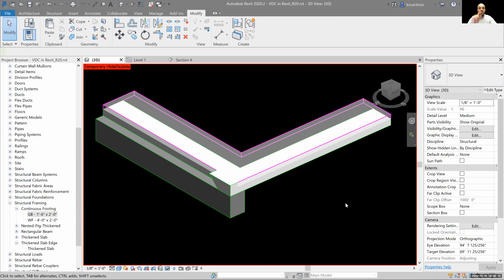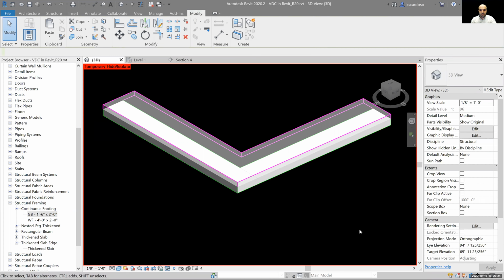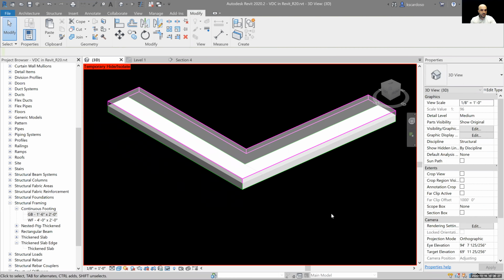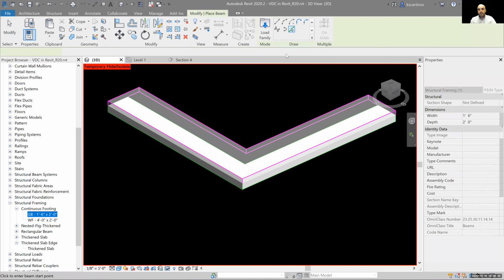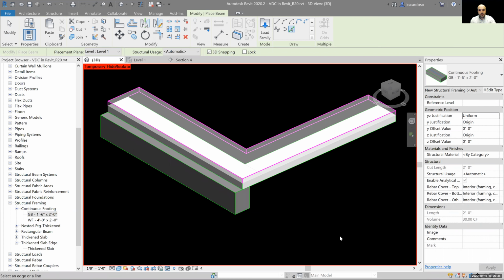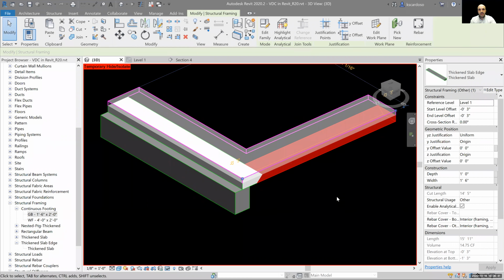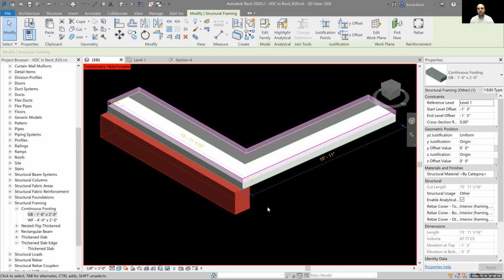Okay. This doesn't happen when Revit sees that analytical line as being in a completely different place. So let's do an undo and delete both of these beams. And now we're going to replace those beams. Grade beam, drag and drop. Pick lines there. And now I'll just pick that bottom edge. You see how this thickening didn't misbehave? Because their actual analytical line, the location line, is at a completely different location than the actual beam.